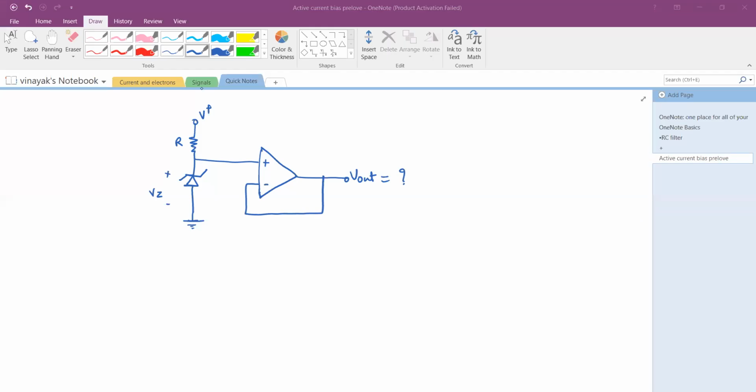Hi there. So we are talking about our circuit analysis session. Here on the screen, we are finding ways to generate reference voltages. This time I'm using the Zener diode, although Zener diodes are seldom used because they are noisy. Also, if you want to generate a reference below 2 volts or something like that, using Zener is not a viable option. So we are asked to analyze this circuit.